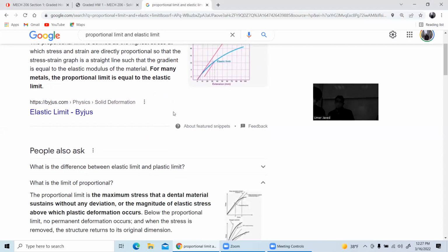And also, I couldn't get the safety factor. Oh yeah. For example, if I tell you that this is a solid metal object, it yields at a certain stress, right? When I say yield, I'm really going to the limit. I really don't want to get into that zone where if I put stress on it, it doesn't come back to its initial form. So I really don't want to get beyond the yield point.